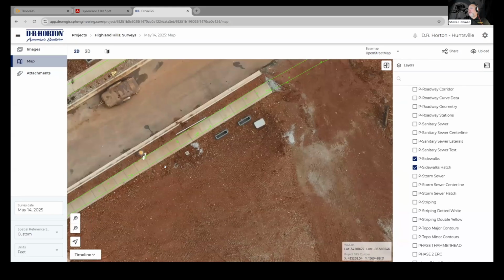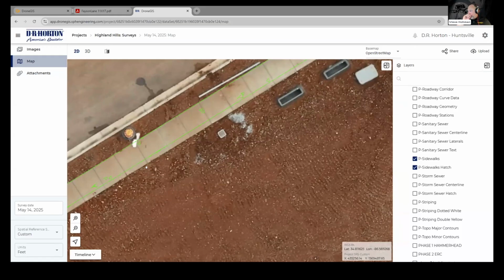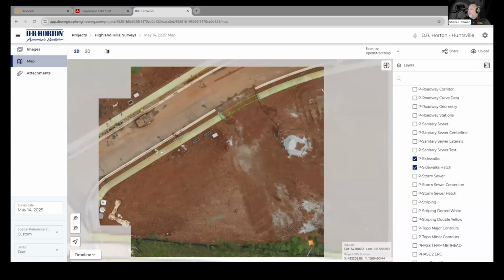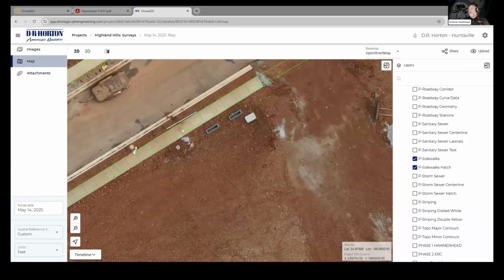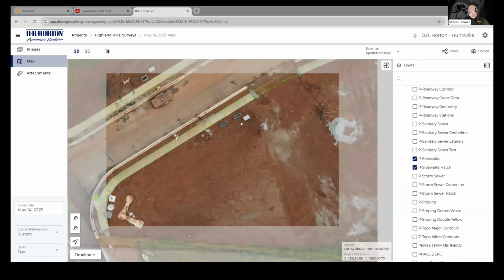And that's the important thing too, is having the skill set to verify what you're presenting, because you're asking someone to make informed decisions on this, and being able to present the facts is important. But we measured this, and sure enough, had a variety of options. Did the design change? And we have an old design file. Did the person who put in the sidewalk, are they normally used to putting in 5s, and they said, okay, I got to put a sidewalk in. Here's my markers. I'll build the forms and I'll make a 5-foot sidewalk when it should be 4.